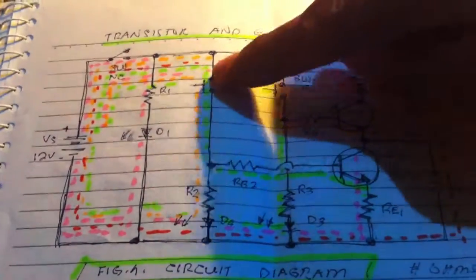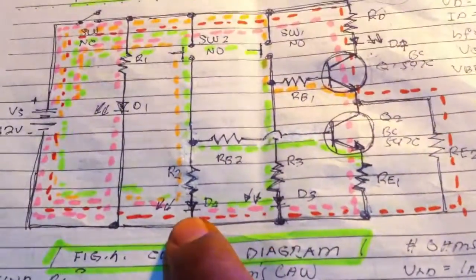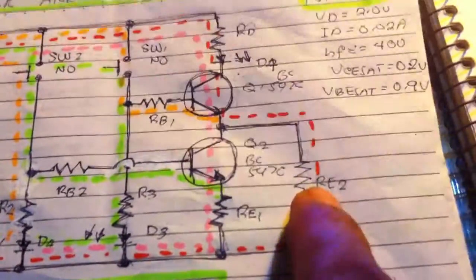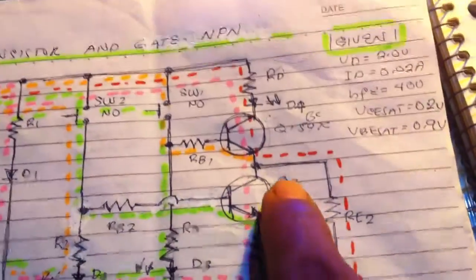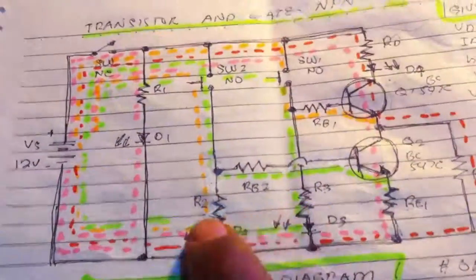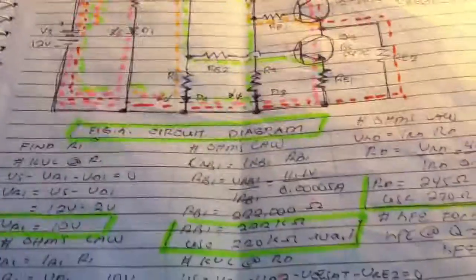The push buttons are there, base resistors, and the LED, the red one, connected to the switch. And we have this bias resistor and also a pull down resistor here to eliminate some sort of leakage current, and at the same time it protects the LED. The resistor here is for the LED power on indicator, that is the blue one. And we also calculated the values of all the resistors here.